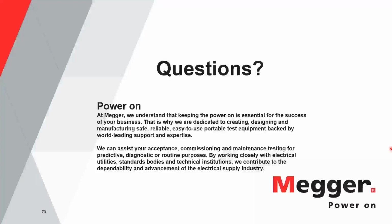Okay, when we're talking about interwinding capacitive test, we are making a reference that if something flags up during the interwinding capacitive test, you may try to correlate results with a capacitive and power factor test. Now, you need to understand that the way we're looking on SFRA is different to the way we're looking in a power factor test. When you do a power factor test, you will short the windings, right? And you will basically create one single electrode with equipotential energy, or electric field, on all three phases at the same time. In this case, we're looking at winding by winding.